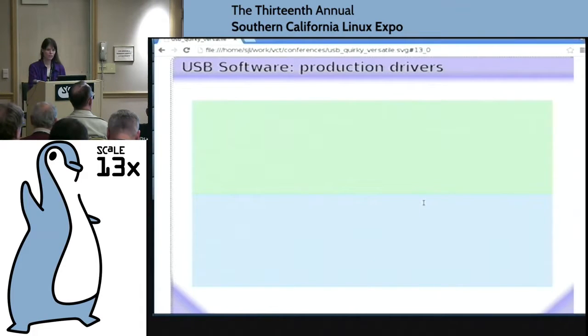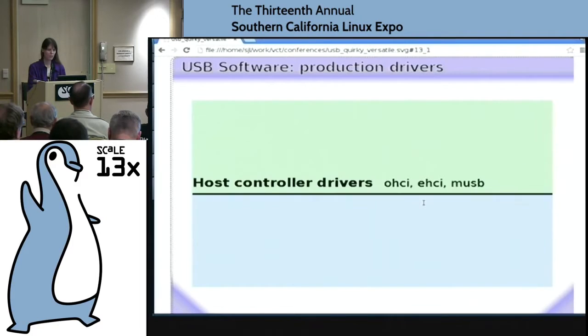Let's talk about the actual Linux side. What are the drivers that you're going to be using if you design a system that has USB in it? Well, at the very bottom of the stack, you have your host controller drivers, which might be similar to the ones you use on the desktop, namely the OHCI, EHCI, and in rare cases, XHCI if you're doing USB 3. But a lot of times you end up with this other thing called MUSB, where the M stands